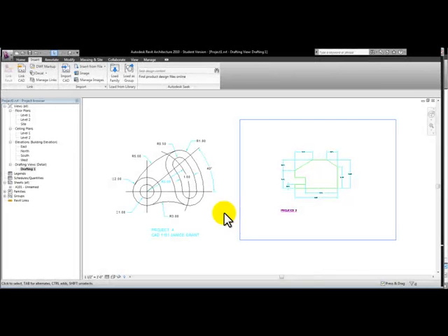Revit can import and link several CAD file types. The Import CAD function is similar to inserting blocks in AutoCAD. You can insert or import a CAD detail and then explode it so that it becomes a permanent part of the current drawing that you're in. Or you can link a file similar to XREFs in AutoCAD where there's an actual link. If the drawing changes in the original drawing and is saved, you can, in Revit, reload that file.